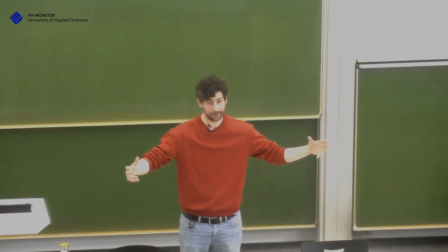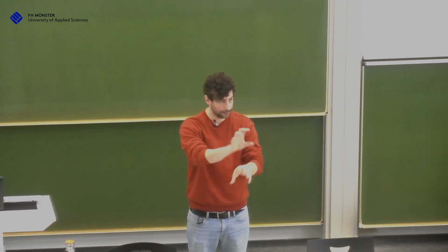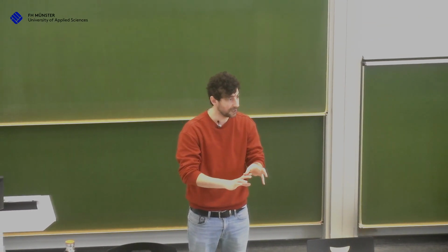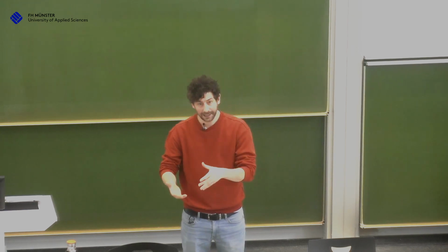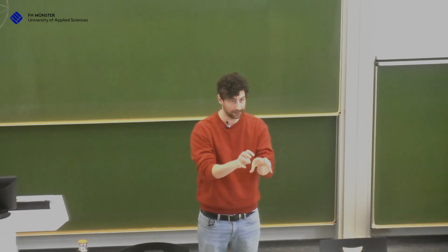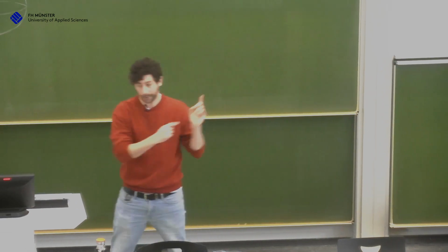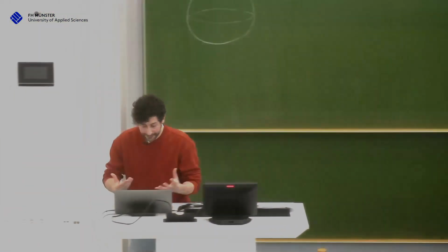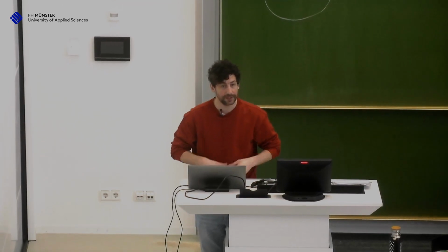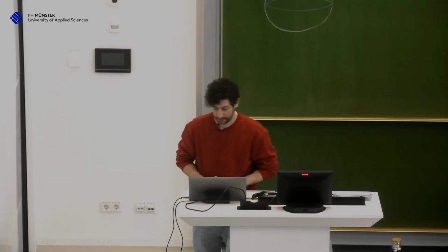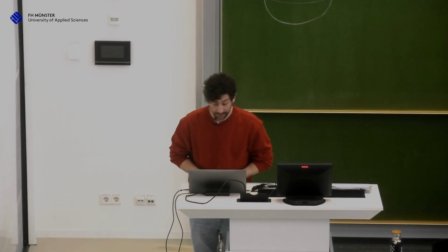Why? Because wide size distribution gives better packing of the particles, right? Less gaps. And it was made for black ink, and black ink needs good packing of the particles to be very intense and very black, right? And here we want to have the other way around. So it's again the size distribution, and we want a process which comes up with a narrow size distribution. And they said, okay, they have a process.